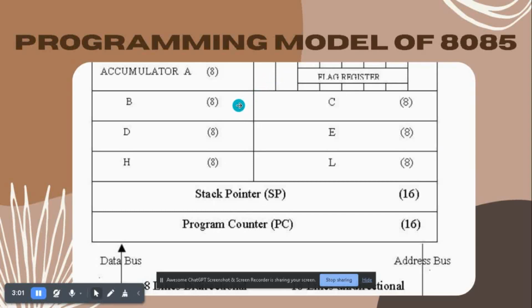Now we have 6 general purpose registers which are B, C, D, E, H and L. All general purpose registers are of 8-bit in size. Then we have some special purpose registers which are stack pointer and program counter. Both of them are of 16-bit in size.